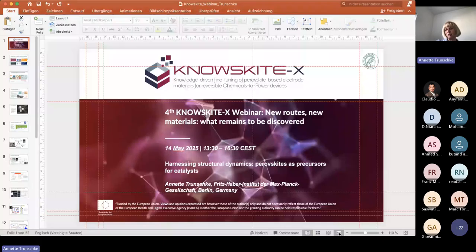At the beginning, I would like to emphasize that catalysis is a multi-dimensional phenomenon. Our active site is, regarding the size, in the order of magnitude of an angstrom, and the elementary reactions are very fast, in the order of magnitude of femtoseconds, but it sometimes takes reacting molecules hours or minutes to enter the reactor and to diffuse to these active sites through the pore structure of the catalyst.